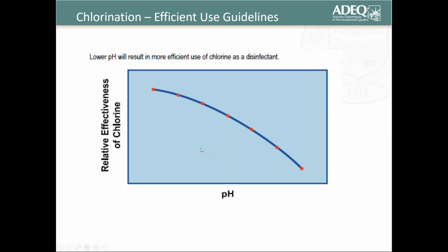And I suggest you keep in mind the water quality, let's say drinking water varies in its pH. So some parts of the states have a more alkaline water source. So there's going to be more chlorine needed to be effective in that.